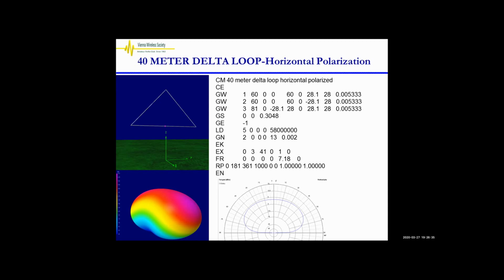So what I did is I used the program to basically, I had a fixed circumference of wire, but then I changed the length here up and down and moved this bottom wire up and down relative to the apex to see if I could get the optimum impedance matching for what I did. So this is the way it works.